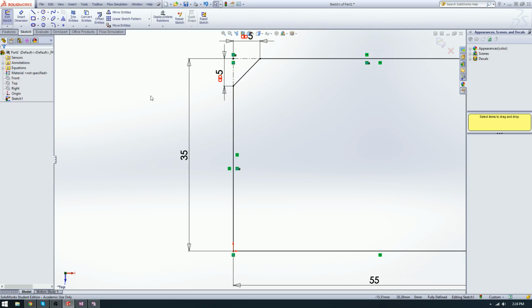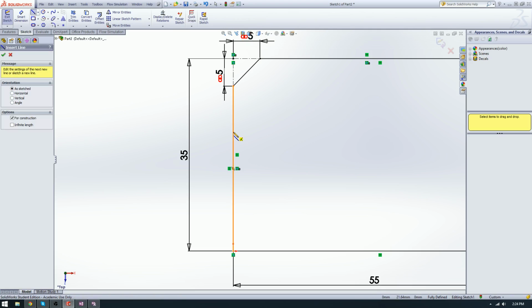Basically, just hit escape a bunch of times to get back to where I was. If you go to draw a line, okay, and you've only hovered over this line, SolidWorks will only try to use this line. Now, if you want to bring other things into the equation, simply highlight over them. So now I've highlighted this line. I'm not clicking anything, just literally going over it. So now SolidWorks knows that I'm looking at two different lines. The original line right here, correct? And it also knows to look for any points related to the other line that I had highlighted at some point. Now you'll see when I'm highlighting at this midpoint, it highlights the entire center line that I drew.